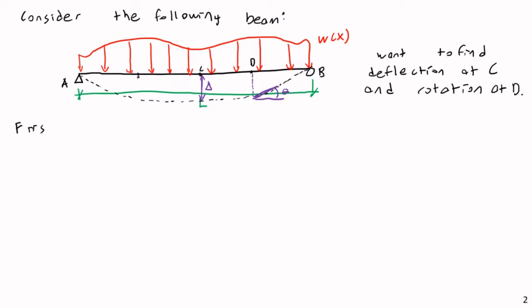Oh, and also I will indicate that we have a little dx here. This is going to be solved by integration. For a truss we use summation because they're individual members, each carrying a single member force. But with a beam, we're going to use a dx, a differential element x, at position coordinate x. So we are going to integrate our way across the beam, so we'll have a differential element dx, a distance x from the 0 side.